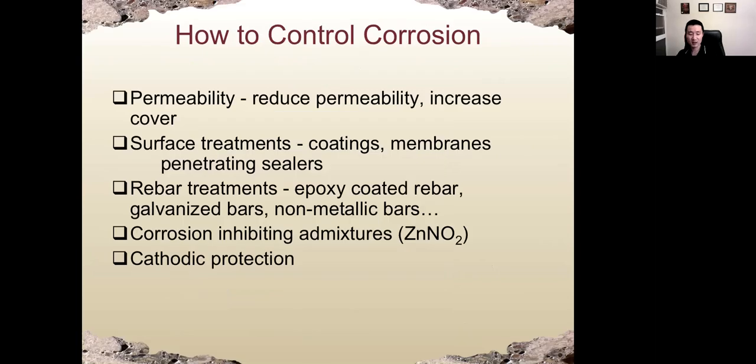That's another method for cathodic protection. We could use a battery, for example, to provide extra electrons, so all the steel reinforcement will become cathode. So this is a very basic introduction of corrosion of reinforcement in concrete.